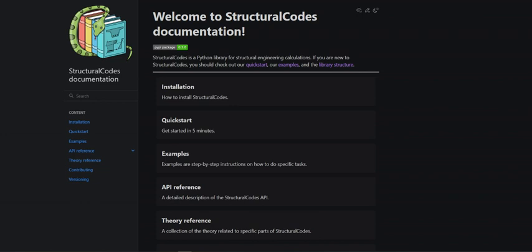But we can also simplify that. I will do a new import on the top here. We will add a reinforcement line. You could probably guess what it does. It adds reinforcement along a line. So we could do geometry equals add reinforcement line.